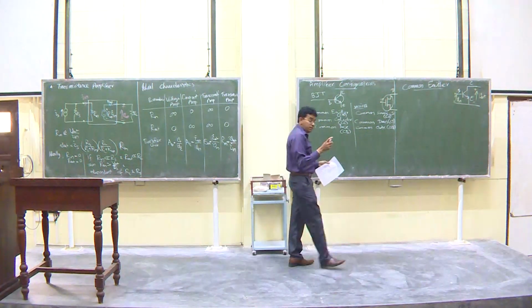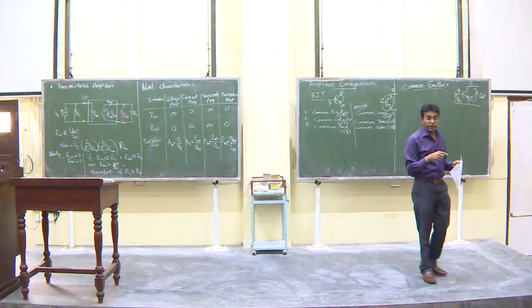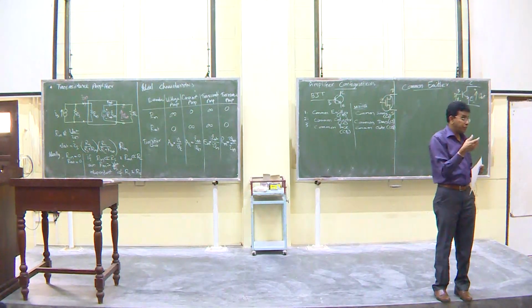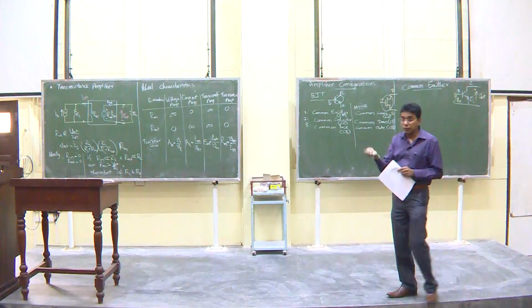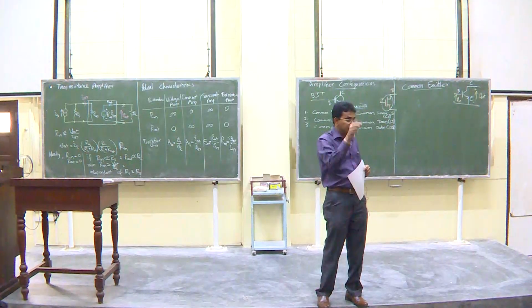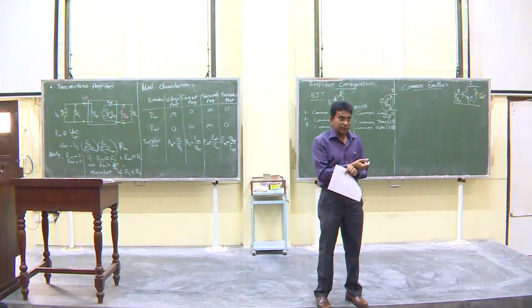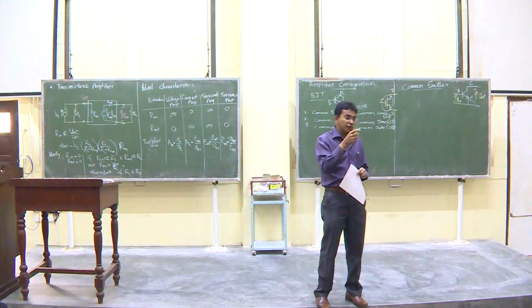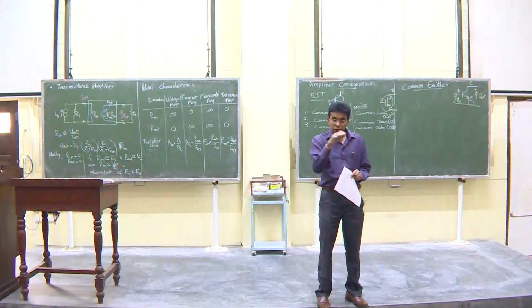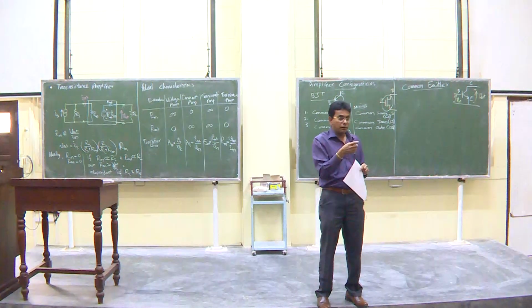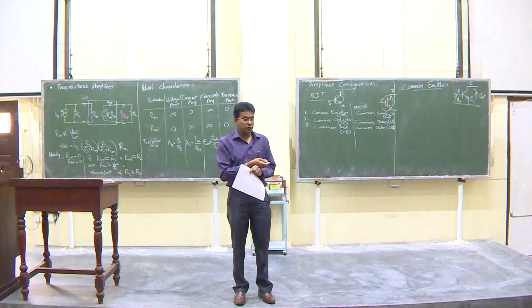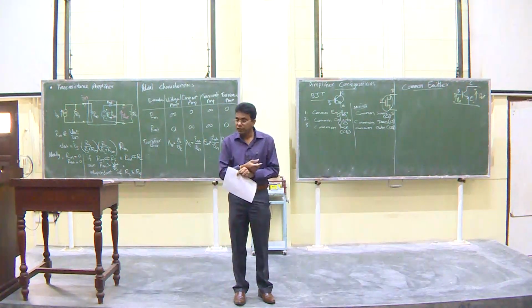Now, sometimes, for example in the example that we did, we had an emitter resistance. We have the emitter resistance as a feedback resistor to improve the thermal stability of the circuit. But in that case, we put a capacitor bypassing the resistor. So again, though there is a resistor there, we can consider for AC signals the short-circuited capacitor makes the emitter the ground. So that's again the common terminal. With respect to that, we have the input as the base, the output as the collector.